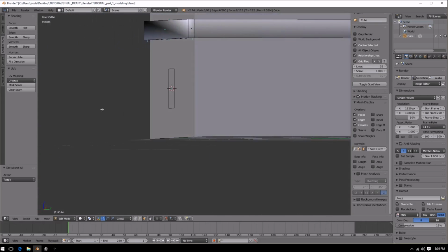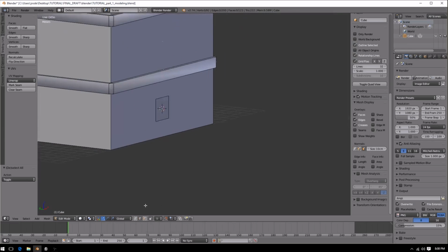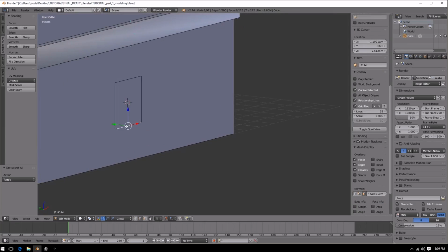It's not going to be something that a user is going to see in game. Next thing I'm going to do is hit the line select button, and we're going to click this bottom line. But first, I'm going to bring this whole plane down to the bottom so that it's easier to figure out how tall we want to make this door. If you recall in the last video, hovering our cursor over this plane and hitting the L, as in Lima, I'm on the line select, so I've got to be on a line here. Press the L button, and it'll select the entire piece or linked objects. Now we'll hit G Z to go down the Z axis, and then move it right down to the bottom there, and that should be perfectly on the bottom plane of our ground.